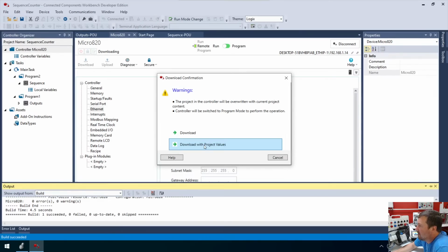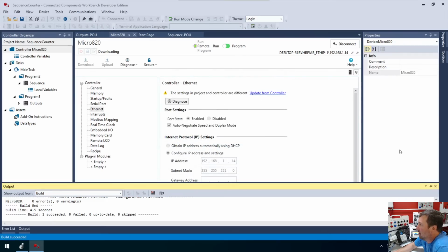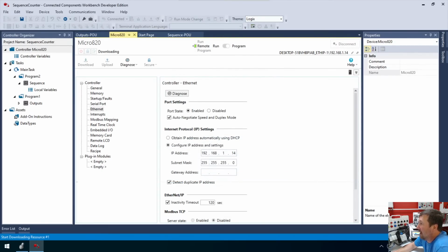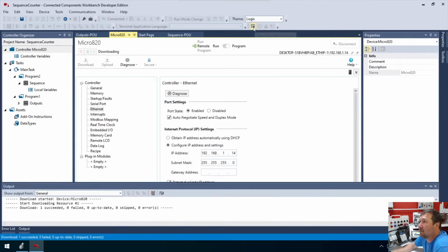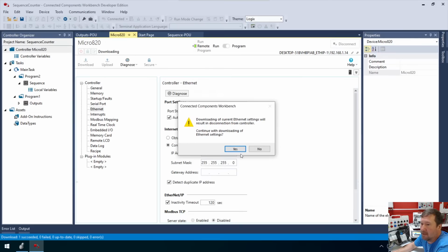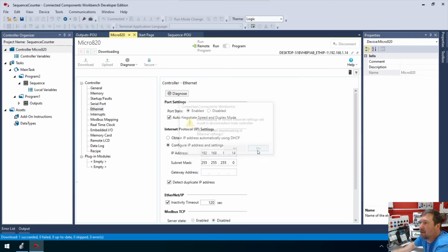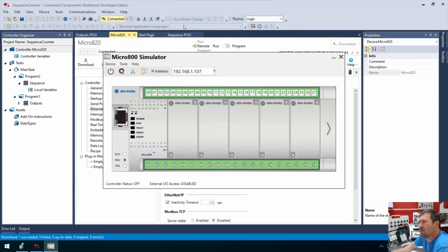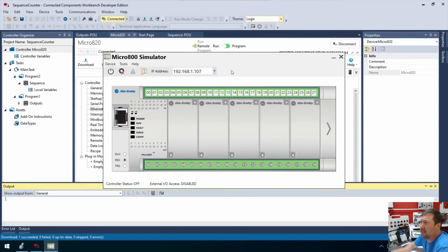You know, there is not a free version of Studio 5000 Emulate. So actually, I would recommend the Connected Components Workbench that we're using right now because it does have a free emulator right here. So as soon as this gets done downloading, I can quickly show. One thing I've noticed about this emulator is it doesn't play well with Studio 5000, and I'm not sure what. But right there's the emulate button, and here is kind of a miniature Micro820 PLC.